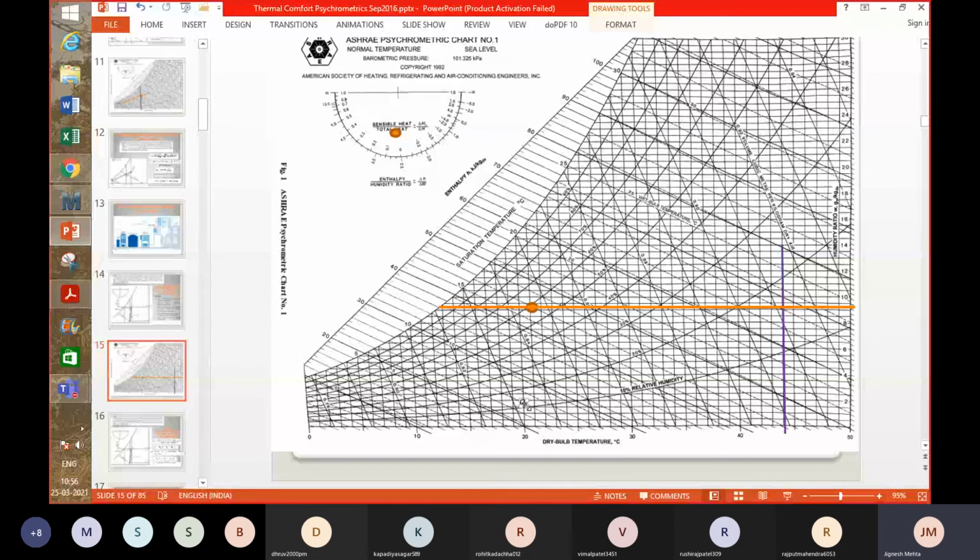Right? So this example was meant to develop more understanding and insight into the steam injection process, air humidification using steam injection. Not exactly adiabatic humidification, but adiabatic steam injection, right? That means from the boundaries nothing is getting lost. It's only the steam which is adding to the enthalpy of air and the moisture of air, right?